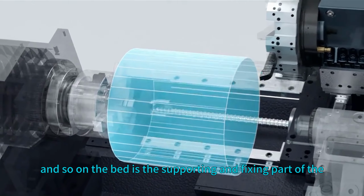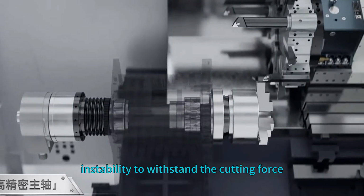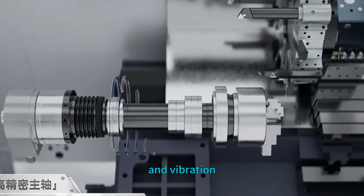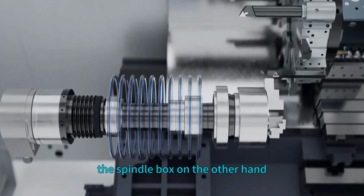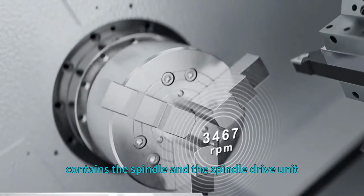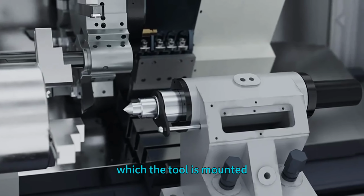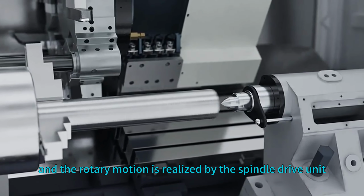The bed is the supporting and fixing part of the lathe. It has enough rigidity and stability to withstand the cutting force and vibration. The spindle box, on the other hand, contains the spindle and the spindle drive unit. The spindle is the axis on which the tool is mounted, and the rotary motion is realized by the spindle drive unit.